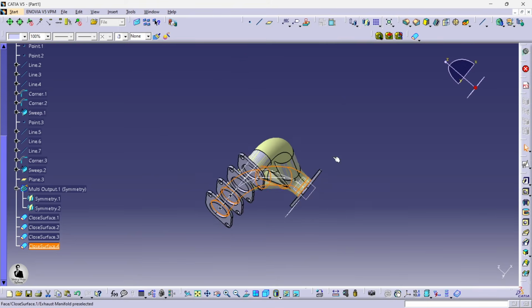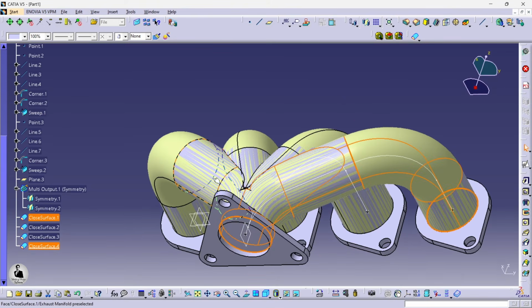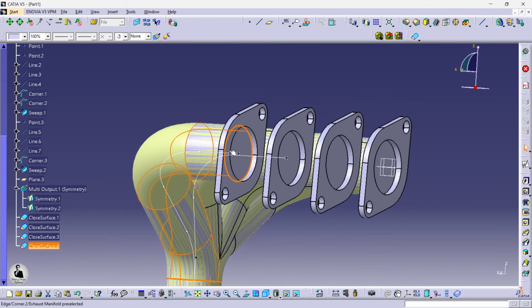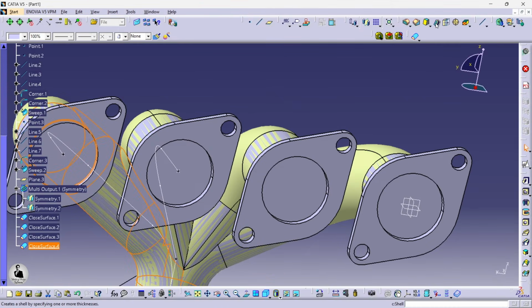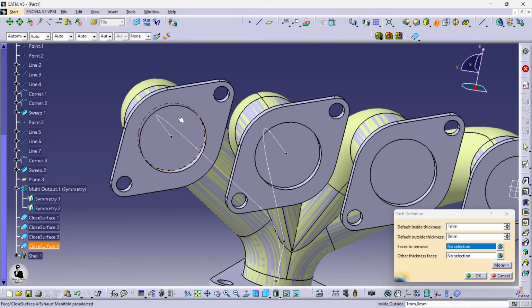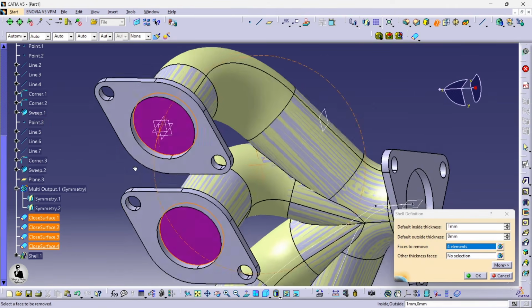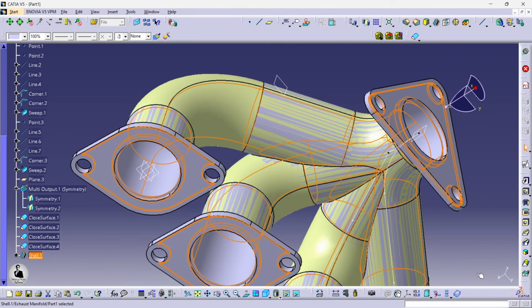The reason why I'm doing this is because there are the 4 channels which are coming from here, right? So it should be distinct, and it should be open for all the parts. So for now I'm going to make a hollow structure inside this. For that we need the option called shell, right? Select the shell part, and this to be 2 mm or more than that if you like. Just see 3.